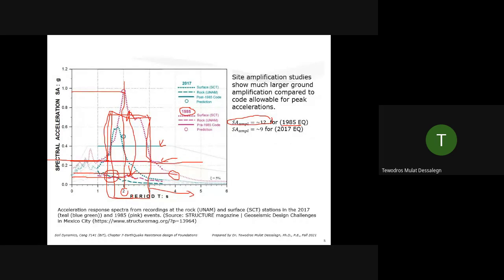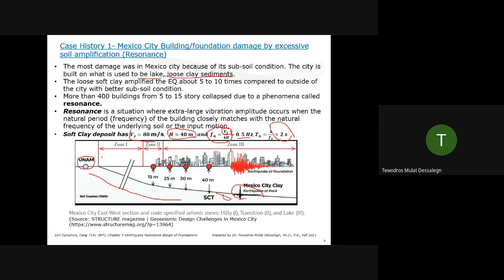As a geotechnical earthquake engineer, you make that decision way ahead of time before anything starts. So you understand what response spectrum is, how you put everything together. That's why we studied wave propagation techniques, to understand the dynamic properties of soil. Once you have the dynamic properties of soil, you can easily find the fundamental frequency and the period of the soil. Now you can discuss. You may not have much detail about the structure or its period, but you can discuss with the structural engineer.